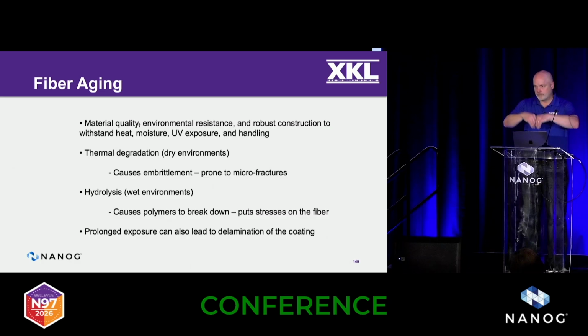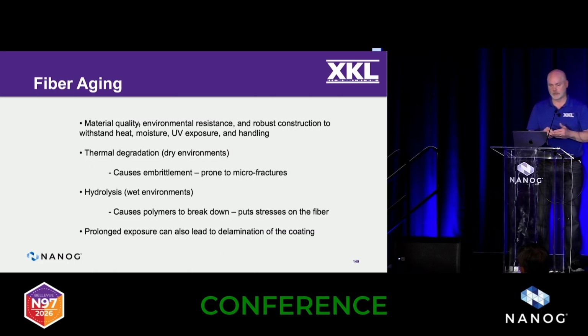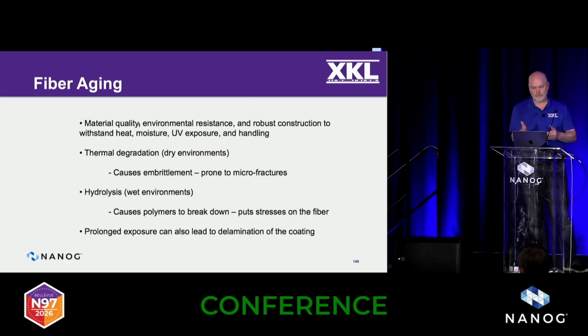And it's going to press on different areas of it. It's going to put pressure on a section of fiber, which doesn't break it, but it's going to affect the transmission, particularly coherent transmission going through that section of the glass. So you have these different environments, like a dry environment, a wet environment, all these things breaking down that outer coating. And some of those materials are really good, and they have a really good life cycle, lifespan, and others not so good. So that's what fiber aging is really about. It's not about the glass, it's about everything else.